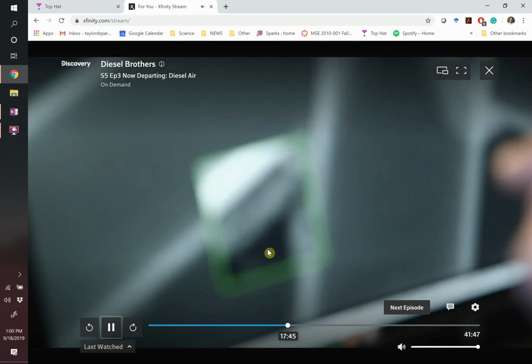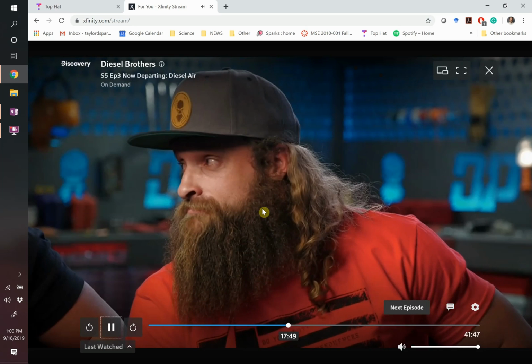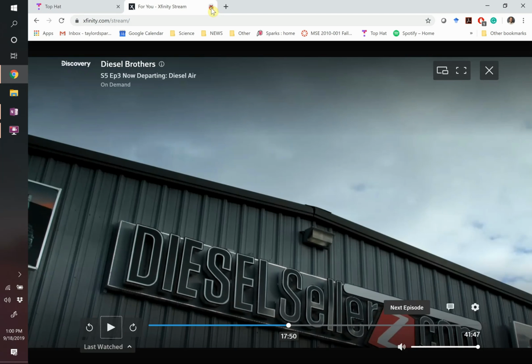So they can see tiny little holes in the material. So this is the exact sort of thing that you could do if you wanted to figure out what's the biggest flaw in your material, right? You could actually measure it and say, oh, there's a flaw in this weld that's a millimeter big, and you could use something like Griffith's fracture equation to predict whether or not it's going to fail, okay?